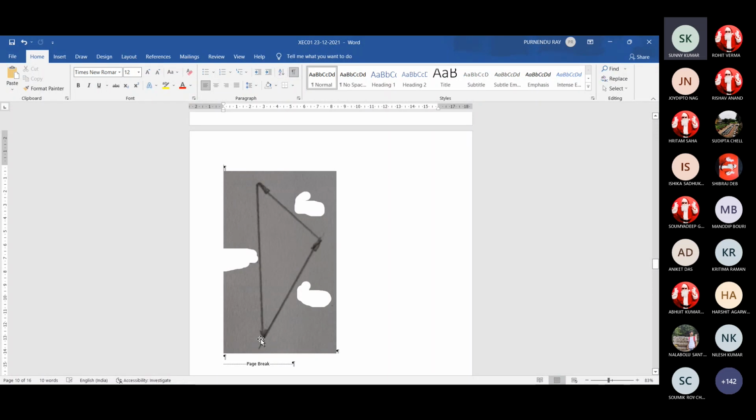Now, what is the difference between all these three cases? C1, C2, C3 are three different locations where we form this triangle, keeping this as the given resultant. It should be the resultant of any other combination of two forces. The first case F1 plus F2, the second case F1 plus F2, the third case F1 plus F2, everywhere we'll get that vector summation as the resultant R. So this reverse process is called resolution of forces.